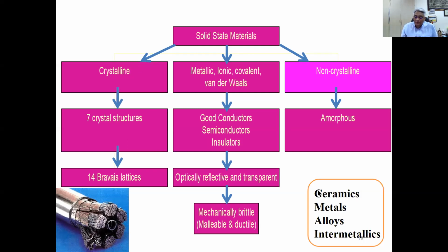Ceramics also are line phase compounds. So I gave the famous example of yttrium barium copper oxide. I said why Ba2Cu3O7. Only for that composition, the cationic ratio of 1, 2, 3, and oxygen ions present in the lattice in a specific way would make that ceramic, which is supposed to be an insulating compound, a metallic superconductor.